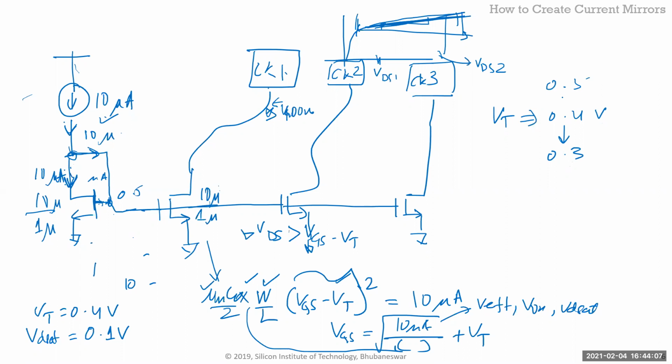If I had the resistor, huge current variation, right? Because the resistor is not changing that way. The VT has changed and the resistor is changing, but the VT is not changing. So huge variation. I didn't actually point that out, but it's changing. But now if the VT changes there, I'm using the exact same transistor very close by. So the other VT is also changing.